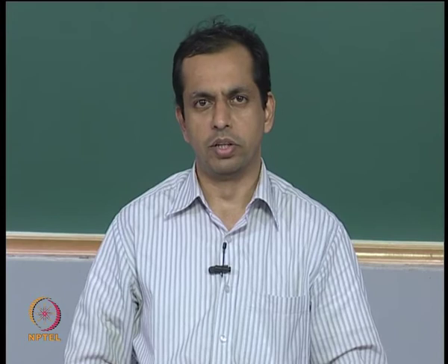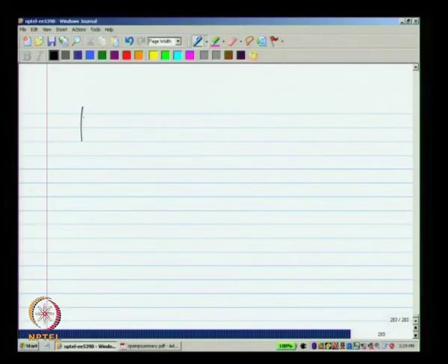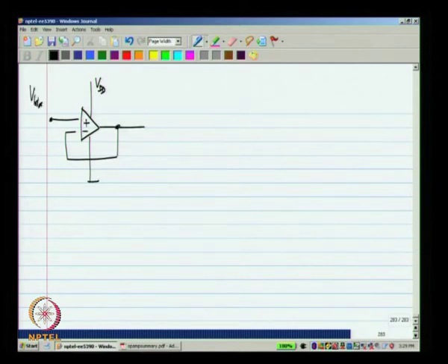Before we go further, a quick clarification on how we connect the load to the two stage op amp. As I mentioned earlier, we are operating with single supplies. So, the input signal and the load must be connected to some bias voltages. We have VDD on top and the ground on the bottom. So, the input will be some Vbias plus Vi.